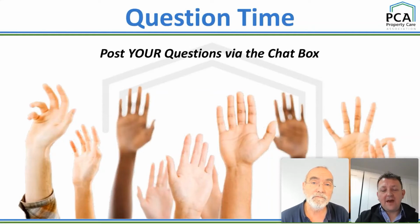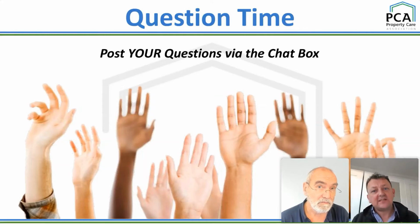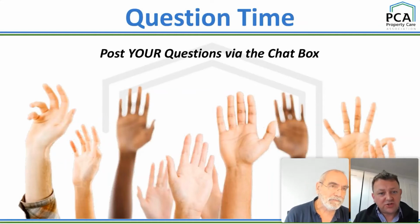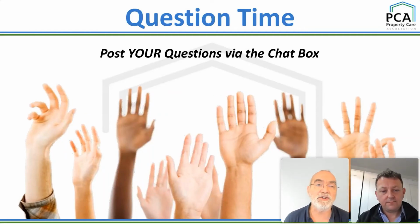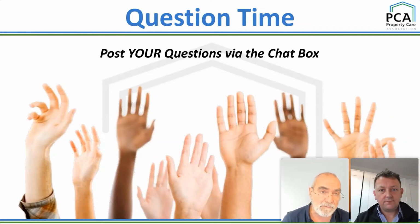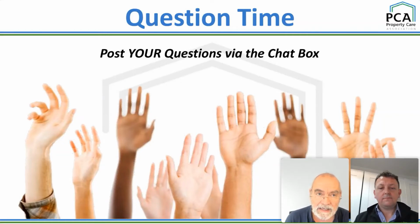Well, sticking with tools and techniques, Nick Wells has just pinged a question asking, are there techniques for testing upstands, thresholds, parapet walls and junctions? Yeah, this again is a really good question. That case study I showed had an upstand parapet on it. One of the NACE specifications actually recommends the wet sponge tester. You'll remember I said that's an effective method in small areas, and you can use that to wet test vertical surfaces. It's not very easy, it's not very quick, but it will work.